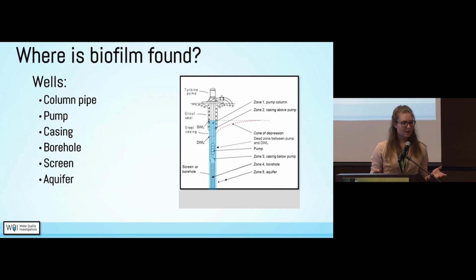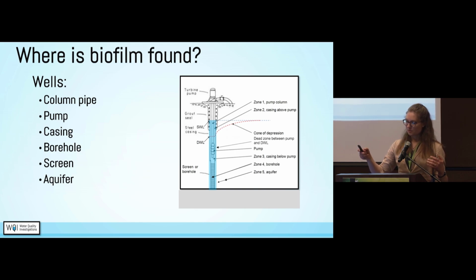Since we're at a private well conference, I wanted to start with wells first. Biofilm can be found in all components of a well. And what I wanted to direct you towards, this is a very basic diagram of a well. We have the SWL, the static water level. That's where the water level is going to sit when the well is not pumping. And then we have DWL, which is dynamic water level or pumping water level. And then when the well pump turns on, the water draws down, and then it's at that lower level.